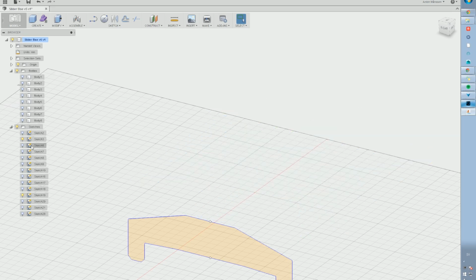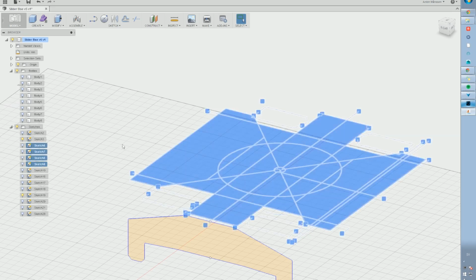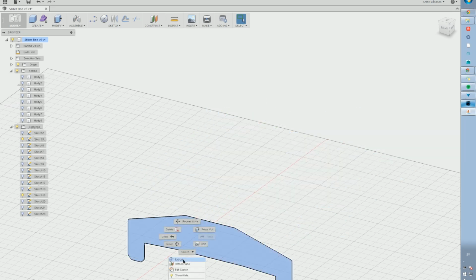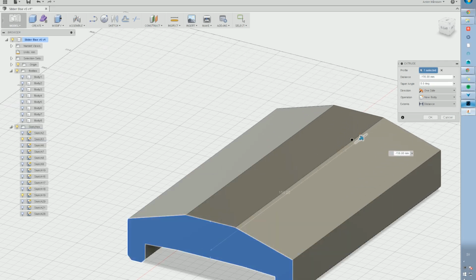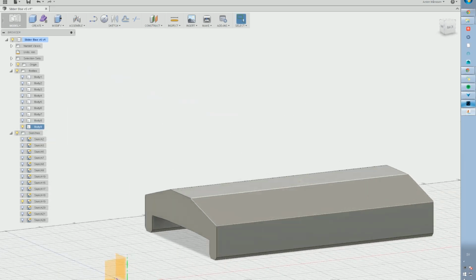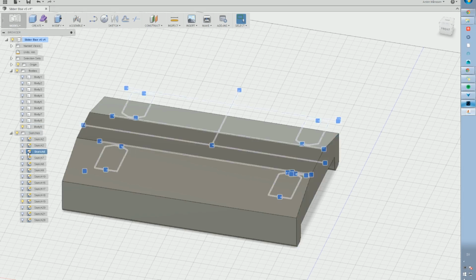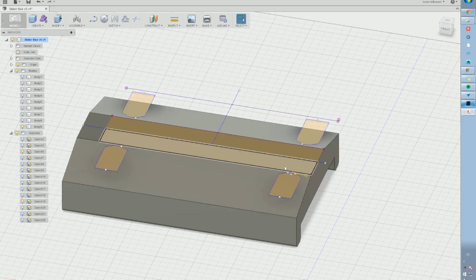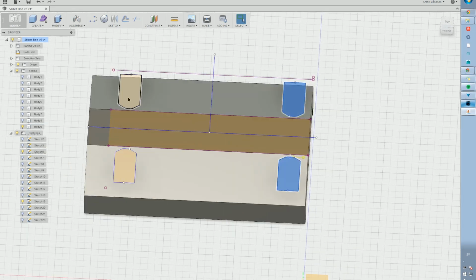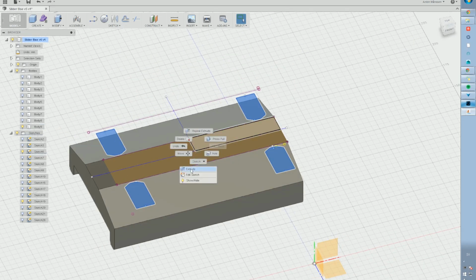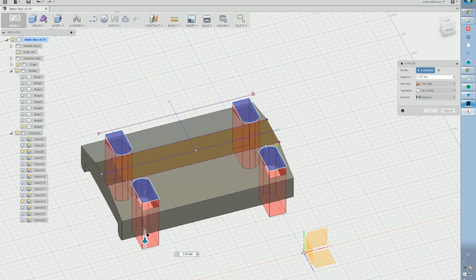You can see here, if you remember, we have these sketches coming later, but this sketch I extrude it, I create a solid, so now we have a 3D model here. Really cool. I use the next sketch, which is this one, to create a few holes. So I take those and I extrude them down.